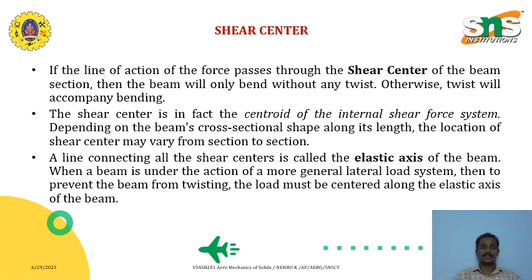The shear center is in fact the centroid of the internal shear force system, depending on the beam's cross section shape along its length. So the location of the shear center may vary from section to section. Let us take a different cross section. The shear center will vary based on the length, thickness, and the shape.